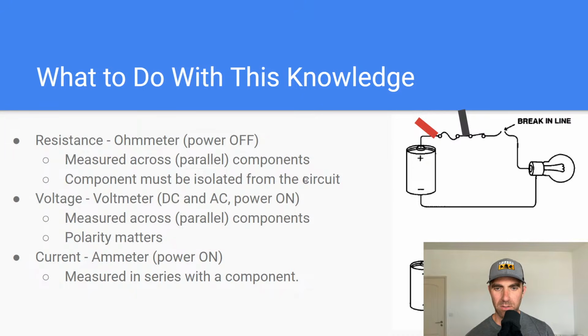And I would say the ohm meter is probably what I have used most often to troubleshoot systems. It's also good to make sure that electrical connectors are pinned correctly, like the pins are located in the right spot in the connector. In that case, the resistance is going to be very, very low, but you're just making sure that there's continuity. So making sure that there are no breaks in the system.